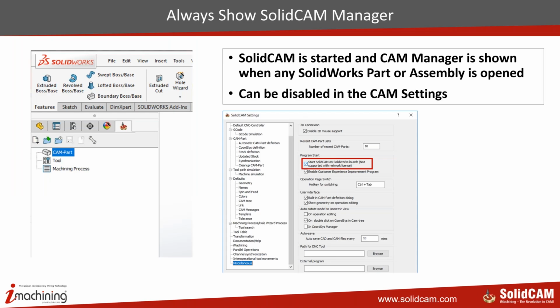The moment you open any SolidWorks part file or an assembly file, SolidCAM is already loaded inside the SolidWorks GUI. You can see SolidCAM is already opened inside the SolidWorks environment. If you don't want this, you can disable it inside the SolidCAM settings.